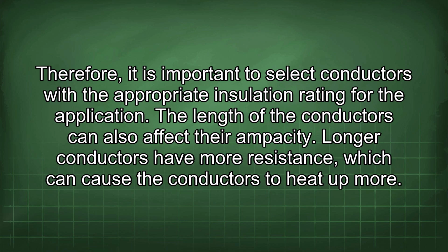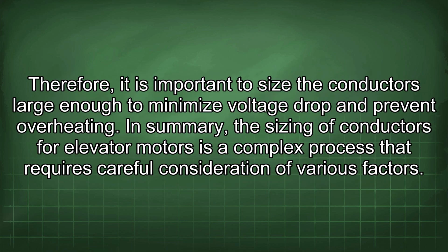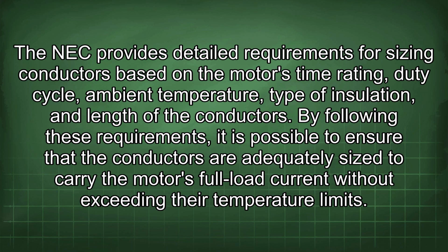The length of the conductors can also affect their ampacity. Longer conductors have more resistance, which can cause the conductors to heat up more. Therefore, it is important to size the conductors large enough to minimize voltage drop and prevent overheating. In summary, the sizing of conductors for elevator motors is a complex process that requires careful consideration of various factors. The NEC provides detailed requirements for sizing conductors based on the motor's time rating, duty cycle, ambient temperature, type of insulation, and length of the conductors.